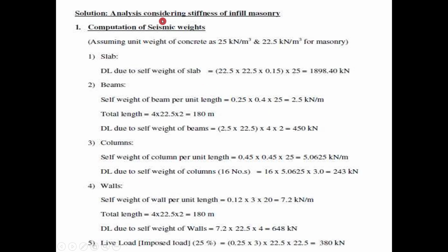So analyzing, considering the stiffness of the infill masonry, you can compute the seismic weight. It's like the calculation of the different dead load and live load of different components as well as the acting forces. We can find the slab dead load by finding volume into density. The beam also, total length of beam into the section area will give you the volume, into density will give you the dead load of beam.